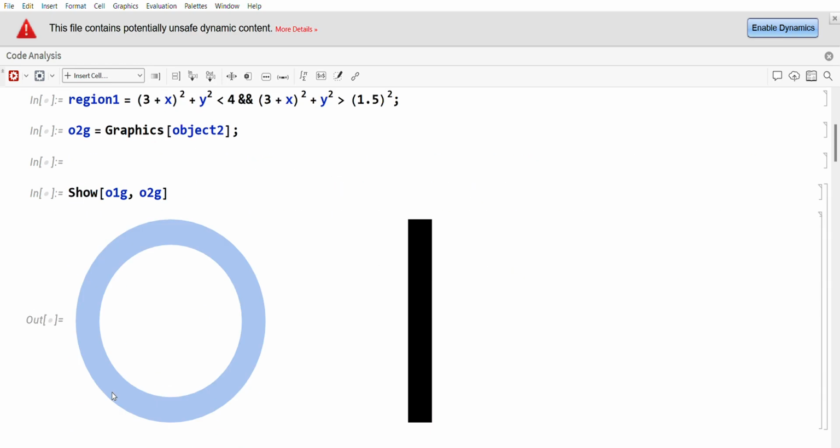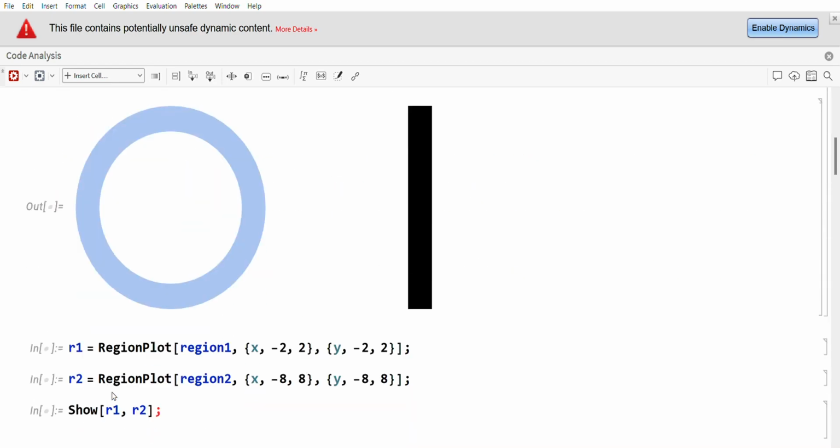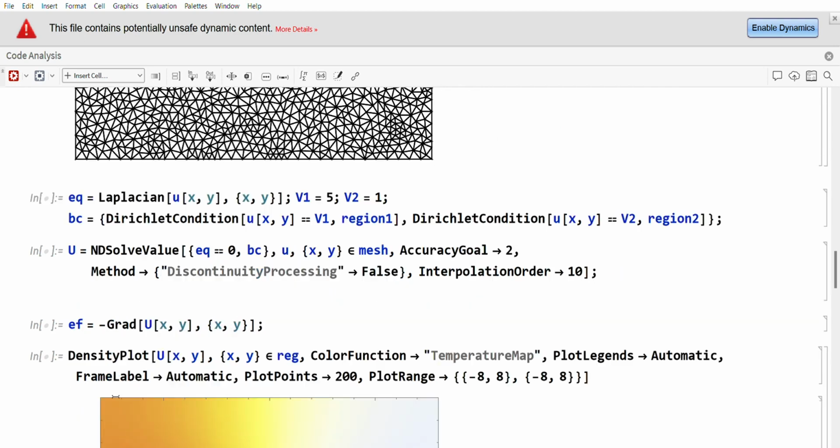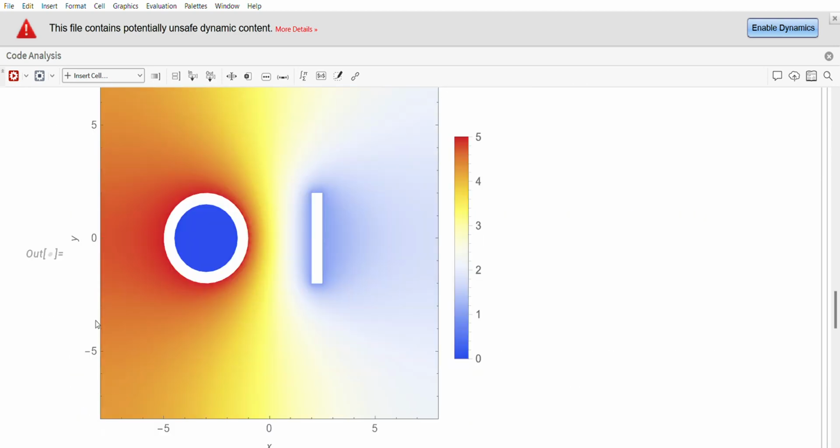Okay, and the last one is this guy. And what theory says, which is an interesting real fact, is that inside we have a shielded area and you should get zero potential. But in your experimental case, it was not the real situation because we want to mimic the electric field in space by using electrically conductive paper, and because the area was connected and this paper was conducting, we got an equipotential, like red, inside. Yes, don't expect this situation.